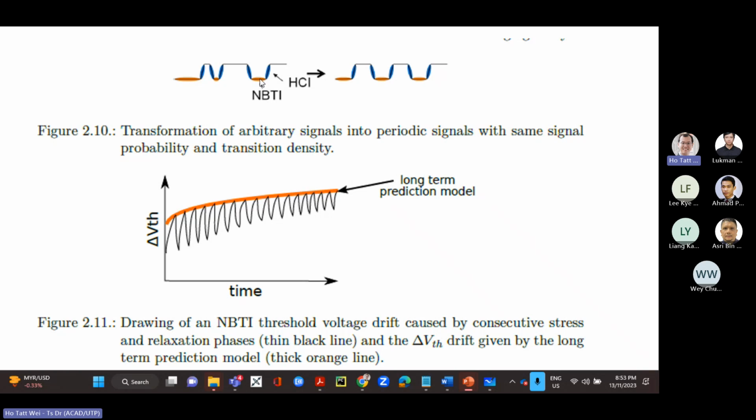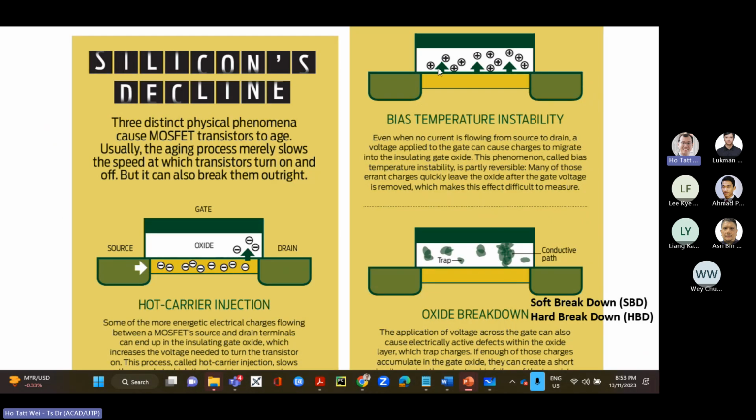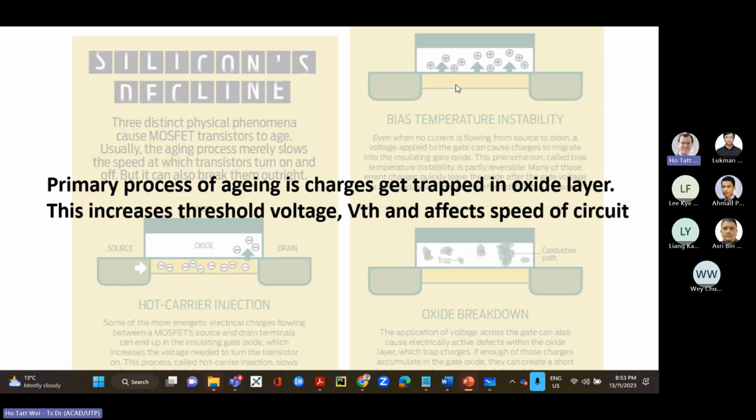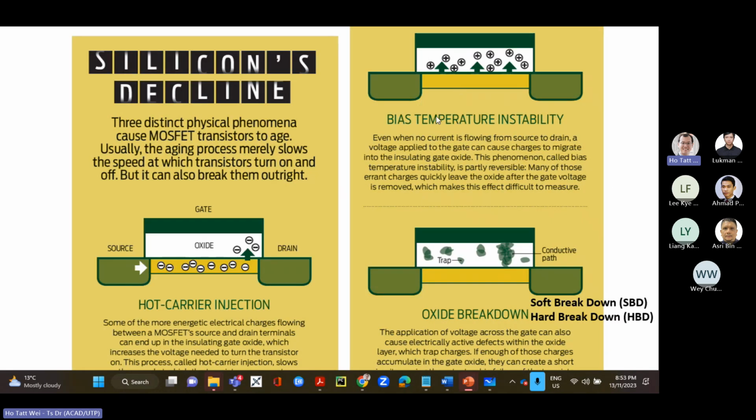And the logic level that's causing the stress is the logic level that is creating the channel, the conductive channel in the device. So BTI is a static effect that happens if you're holding this gate static for a long time. But even if you're switching it, the percentage of time you're spending at logic 1 or logic 0 is really going to contribute. HCI is just how much time you are pumping current through this transistor.